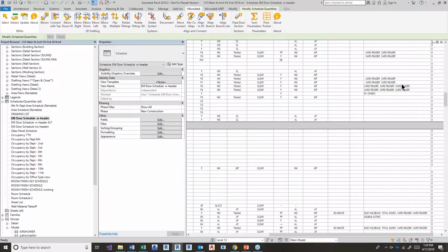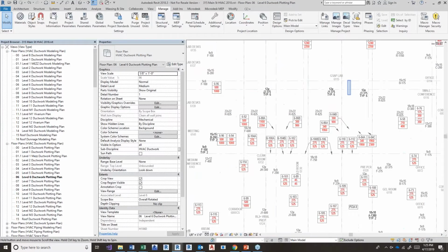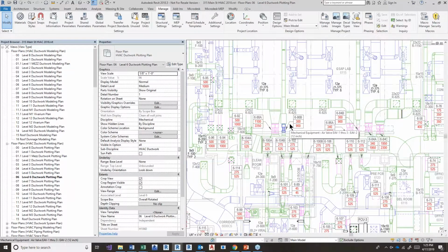So other examples would be, I mentioned earlier, if you're an owner or operator who needs to add barcodes or commissioning information to existing parameters to your BIM model before you integrate it in with your CMS, this is one way to do it. Similarly, we might be able to go into an engineering project, and an MEP designer might be exporting information to give to their manager who may not be fluent in Revit, who's updating information like min and max CFMs and providing that back to them in Excel. Or we could be getting balancing schedules from a commissioning agent, and we need to get the information back into the floor plan for the owner who wants this as an as-built condition.